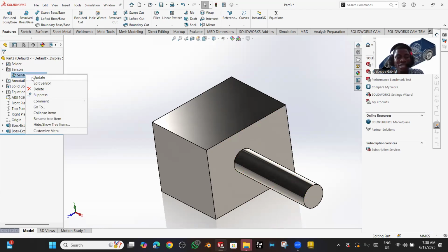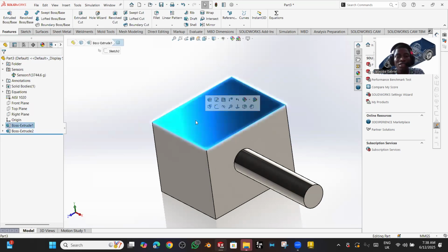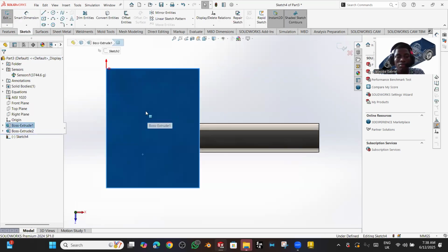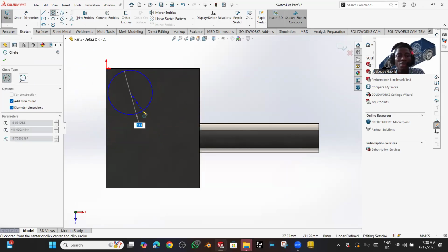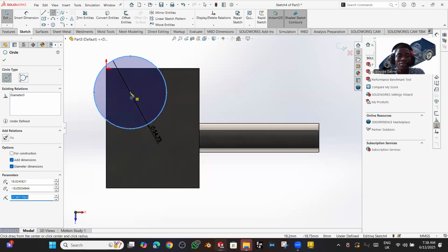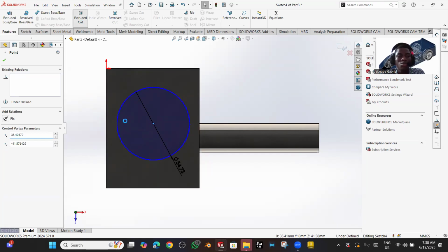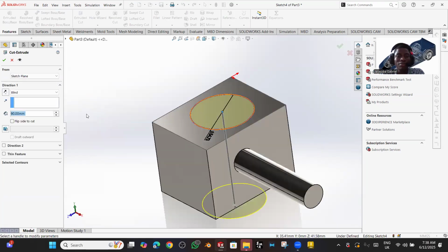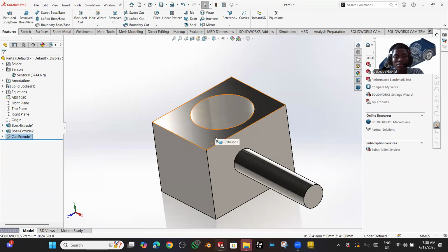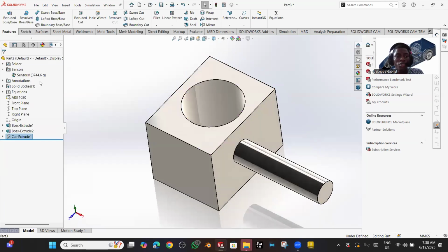If you don't update it, it will take a long time before your sensor will actually read the new value. So just click on update to read the new mass. Now let me create a hole here. Now from 37, we're going to see what will happen. Our mass is going to deteriorate. I want to extrude and cut. So can you see? If I cut that part out, our mass is going to reduce from 37. Right click and update. Can you see? 2443.42. The mass has changed.